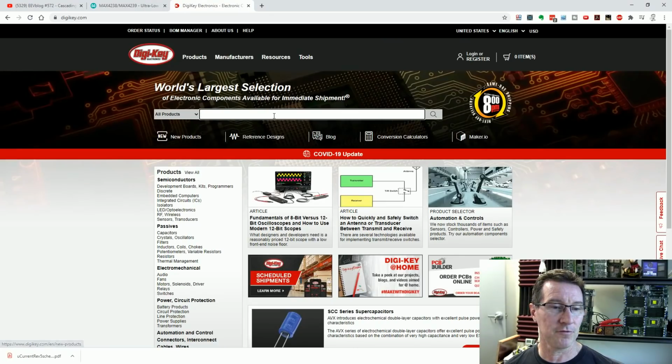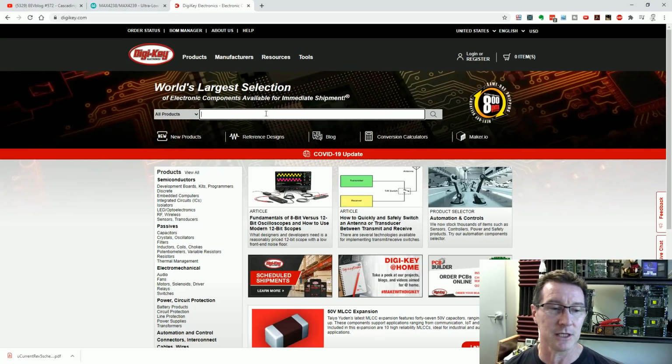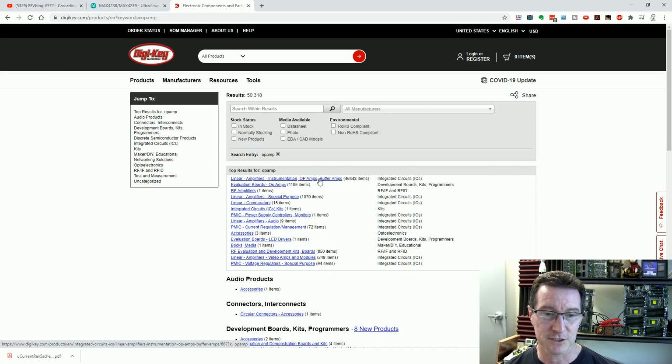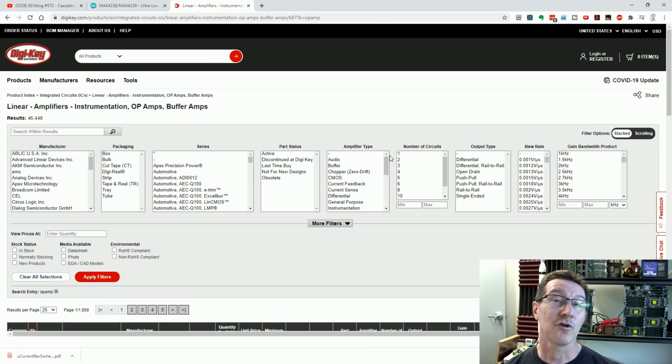All right, who's your favorite provider? Let's just go to Digikey first, shall we? Op amp, 46,000 op amps. Thank you very much. Now, of course, there are 2 ways to do this. One is through your component supplier's parametric search, your Digikeys, your Mousers, your LCSCs, or your RS Components, your Farnell, Element 14, whatever they call themselves these days. They're not always infallible, but you can also go directly to the manufacturers as well. So I might have started this off by going to the Maxim website and using the Maxim parametric search, and we'll probably do that shortly.